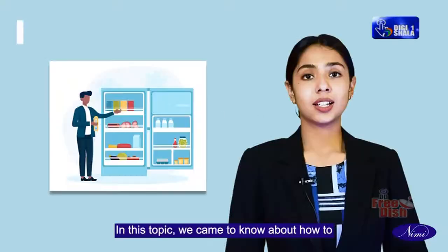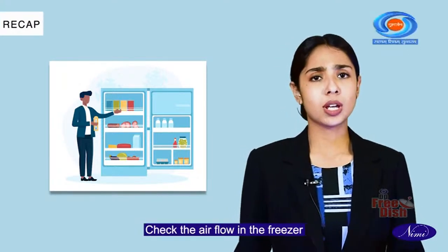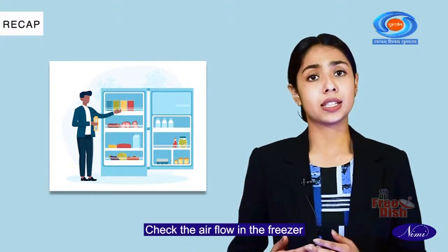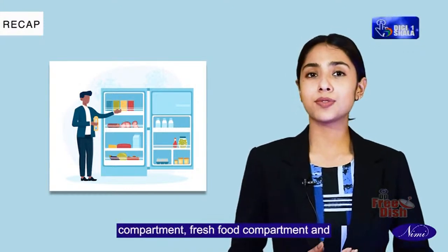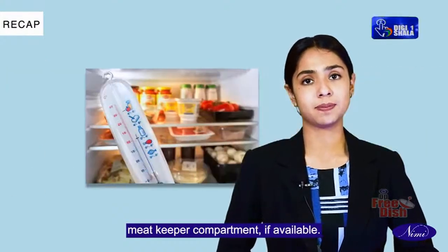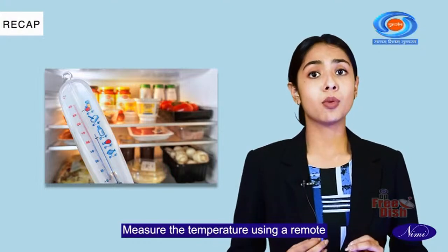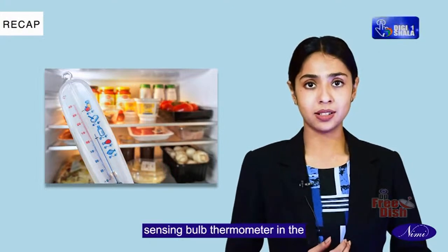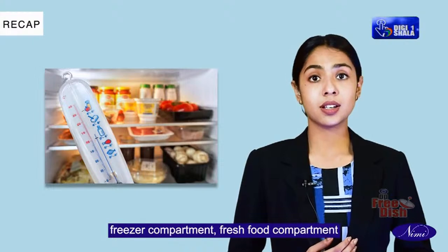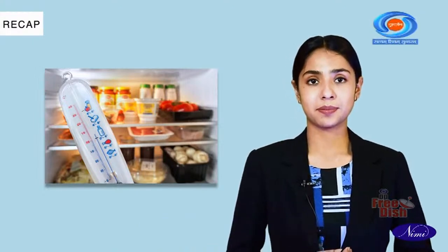Recap. In this topic, we came to know about how to check the airflow in the freezer compartment, fresh food compartment, and meat keeper compartment if available. Measure the temperature using a remote sensing bulb thermometer in the freezer compartment, fresh food compartment, and meat keeper compartment.